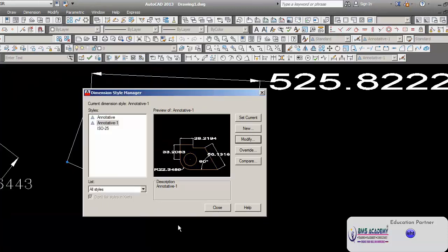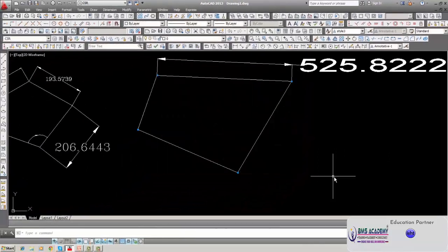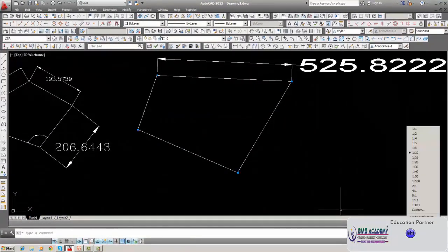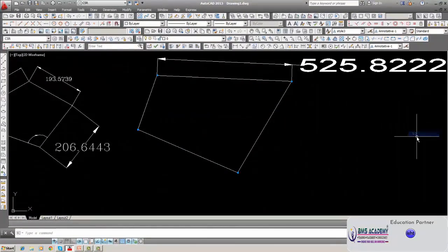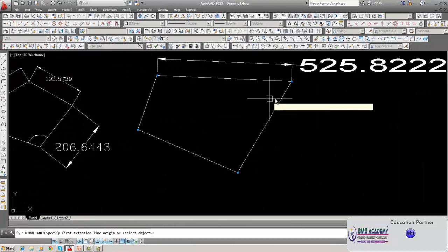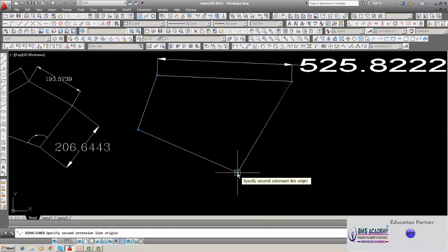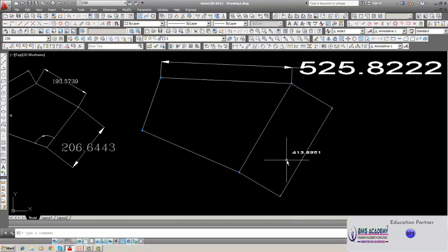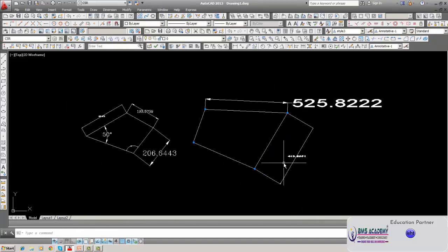That is what is height, text type and width factor and Arial text. Okay. And suppose we change here to 2. I explained to you earlier in the standard style, it has been reduced. So there are 2 things we have to remember. Annotative style, you have to select different, if you want different font, different properties.